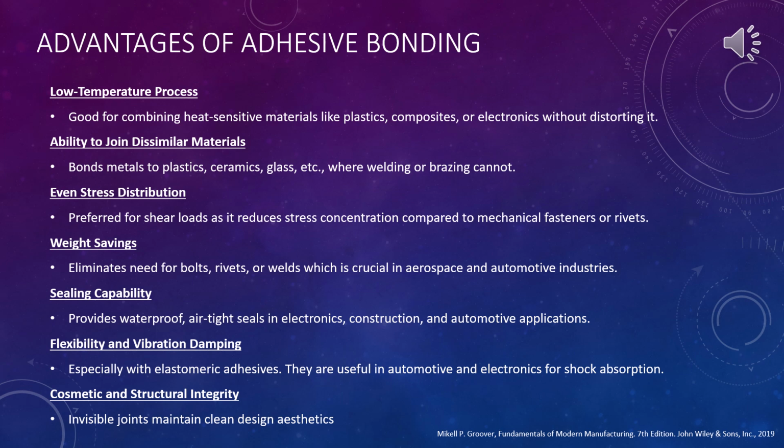Number 5 is the sealing capability. Adhesives provide very waterproof, airtight seals in electronics, construction, or automotive applications. Number 6 is flexibility and dampening. Adhesives like silicones maintain elasticity, which absorbs shocks and vibrations. This is very helpful in electronic assemblies, vehicles, and even medical devices, where protection from constant movement is required.